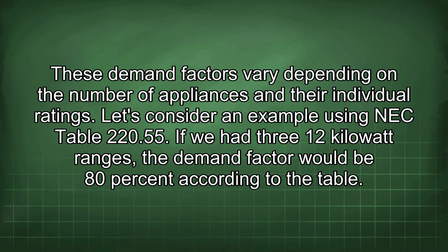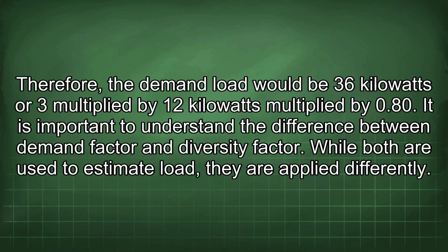Let's consider an example using NEC Table 220.55. If we had 3 12 kilowatt ranges, the demand factor would be 80% according to the table. Therefore, the demand load would be 36 kilowatts, or 3 multiplied by 12 kilowatts multiplied by 0.80.